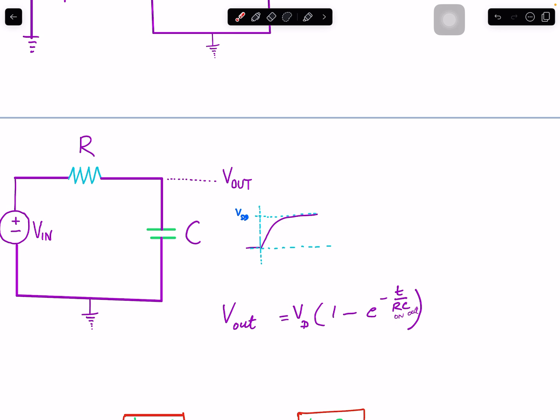I don't want to get into lengthy equations, but if you look at the current through the capacitor, which is C dV by dt, right? Then you multiply that with R and equate it to Vn and calculate the output voltage that varies with time. This becomes a differential equation of current. If you solve that differential equation to find V out, the output will be something like this. What is V out? So this is V out.